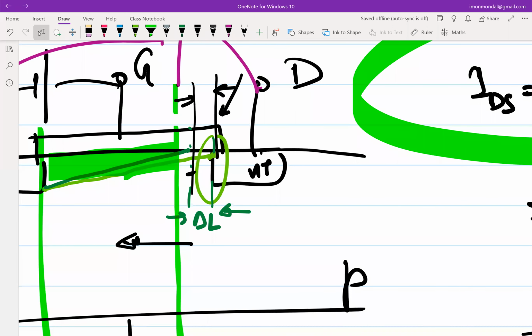So one obvious question is, since the current is flowing, there is mobile charge there. Has to be. And that is accurate. There has to be mobile charge there. But when we say we don't have any charge, or we have some charge, it is always with respect to some background. Here, when we say that we don't have any charge, it means we have much lesser mobile charges with respect to the background ionized impurities that are there, right?